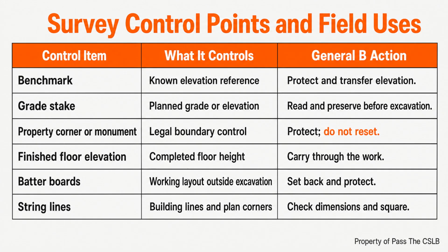That means grading, paving, trenching, sidewalk replacement, and demolition can all create a monument issue before the operator ever realizes it. A small brass disc in concrete, an iron pipe at a corner, or another durable marker may look ordinary to somebody focused only on production. The contractor has to recognize that destroying it can erase evidence that other people rely on.